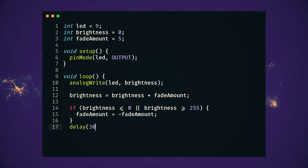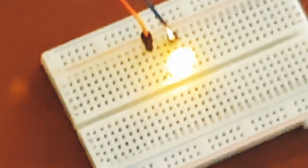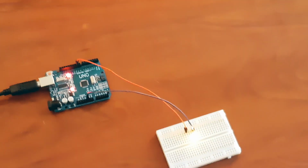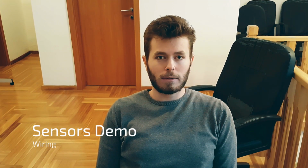So we'll also set the delay to much quicker than a second. This time we'll use 30 milliseconds so we can see the fade amount faster. Alright. As you can see, also simple as that. Now, with the use of some sensors, we'll show you what you can achieve with the Arduino.